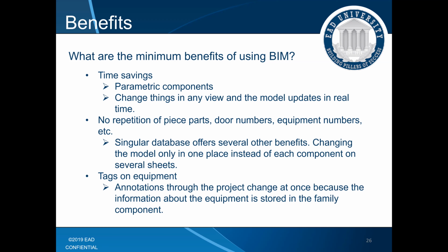If I've had a piece of equipment that is actually dimensioned inside of a model, and on your sheets, it could be from an elevation, it could be from the plan views, all of that information that was with that piece, the tags, the dimensioning, if I erase that piece of equipment, all of those annotations go away. Throughout the whole project, not just on that sheet you're working on. They will remove themselves through the whole project because they're tied to that piece in the model.